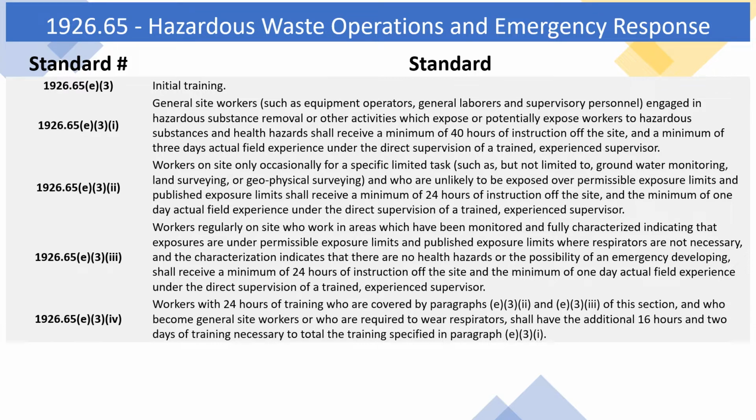1926.65 E3(2) Workers on site only occasionally for a specific limited task, such as, but not limited to, groundwater monitoring, land surveying, or geophysical surveying, and who are unlikely to be exposed over permissible exposure limits and published exposure limits shall receive a minimum of 24 hours of instruction off the site, and a minimum of 1 day actual field experience under the direct supervision of a trained, experienced supervisor.